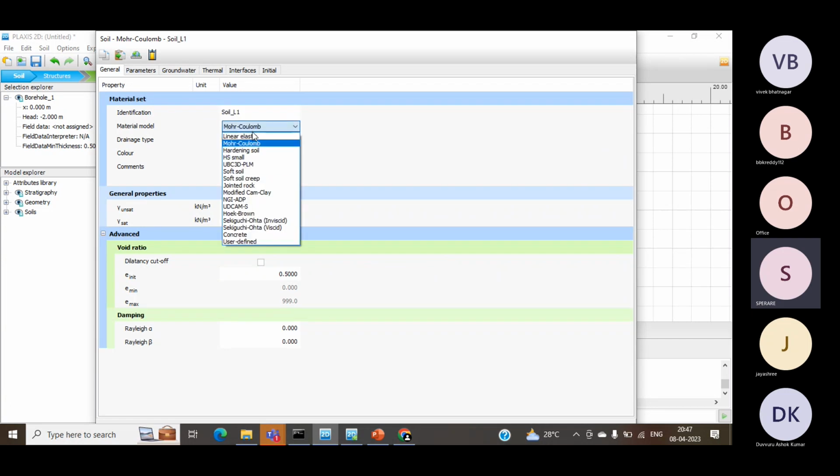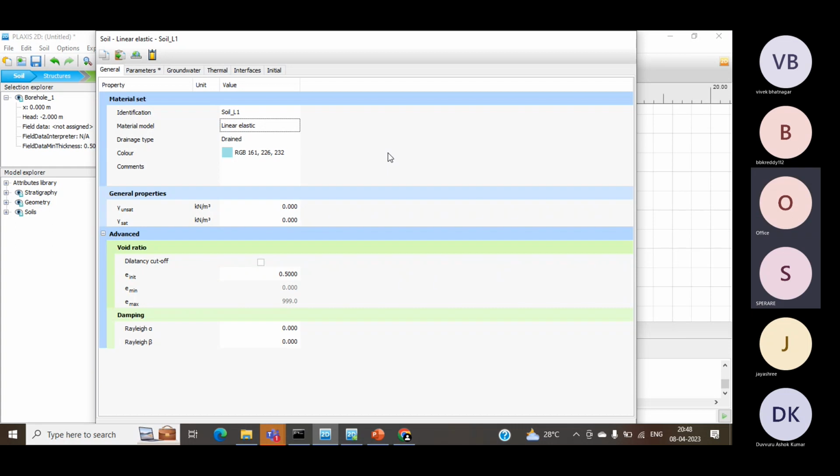And now these are all the models that are available. Let me come to them one by one. If I go with a linear elastic model, what kind of materials can you hint me, like what is a linear elastic model? Hooke's law, material obeying Hooke's law. Exactly. So the one which satisfies Hooke's law is called a linear elastic model. But beyond Hooke's law, what will happen? Elastoplastic will happen.